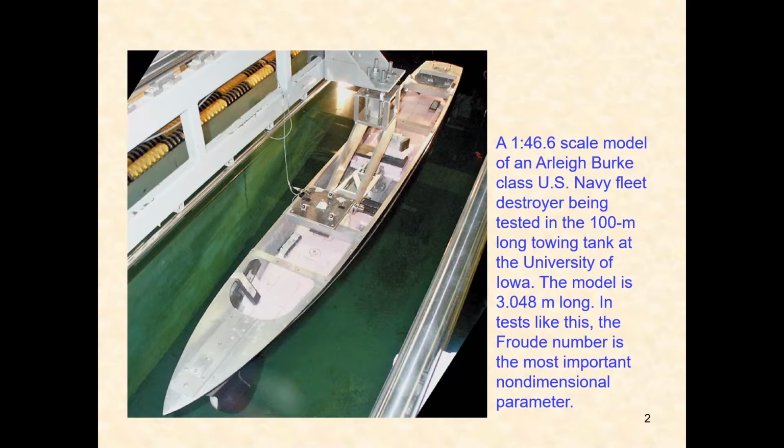So in tests like this, the Froude number, which is a non-dimensional number, is very important for the problem or case where you have open surface or free surface flow, like water in a reservoir, in a tank, or in the oceans. They are all cases where we have a free surface that is not confined at the top, it's open to atmosphere.